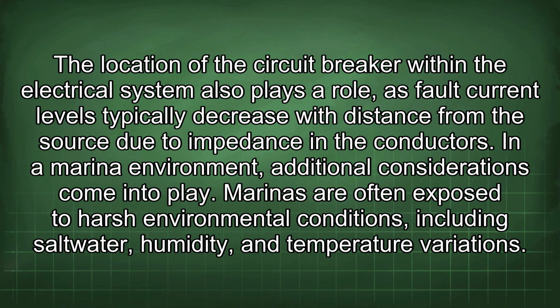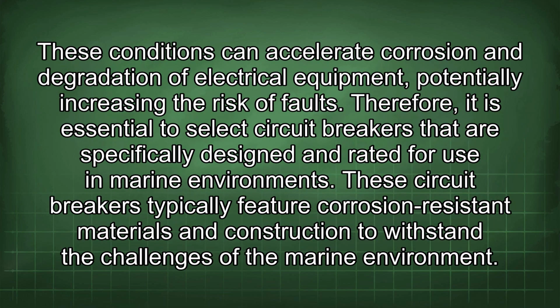In a marine environment, additional considerations come into play. Marinas are often exposed to harsh environmental conditions, including saltwater, humidity, and temperature variations. These conditions can accelerate corrosion and degradation of electrical equipment, potentially increasing the risk of faults. Therefore, it is essential to select circuit breakers that are specifically designed and rated for use in marine environments. These circuit breakers typically feature corrosion-resistant materials and construction to withstand the challenges of the marine environment.